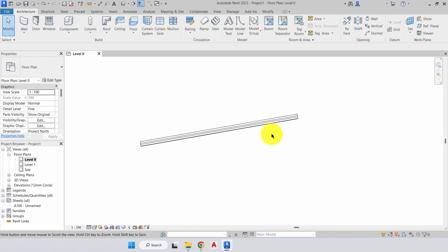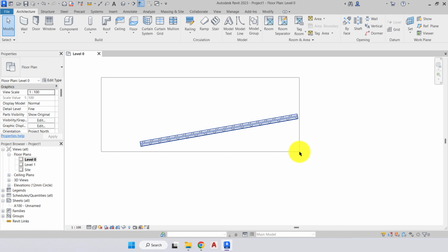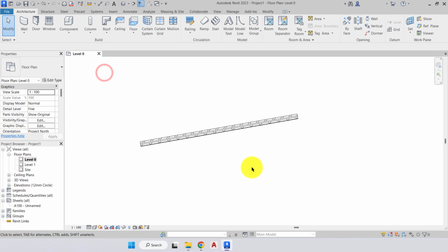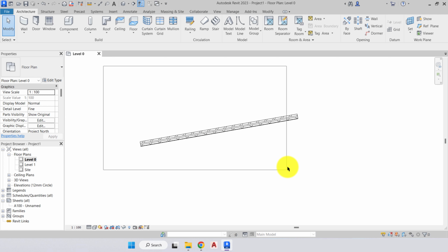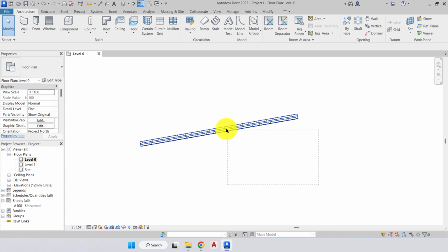And same like within AutoCAD, we have our object selection. So if I zoom in here, our window selection will only select an object when it's completely inside our window. So that wall will only become selected when it's inside. Escape. If I go from the bottom right-hand corner up to the top left, we get what is called a crossing selection. So all I have to do is touch the wall and it will become selected. So in AutoCAD, you click once and let go. In Revit, you click and hold. Click and hold, move to the bottom right. So once that wall comes inside, it's now in our window selection. Bottom right to the top left, we have our crossing selection. We just have to touch the wall.